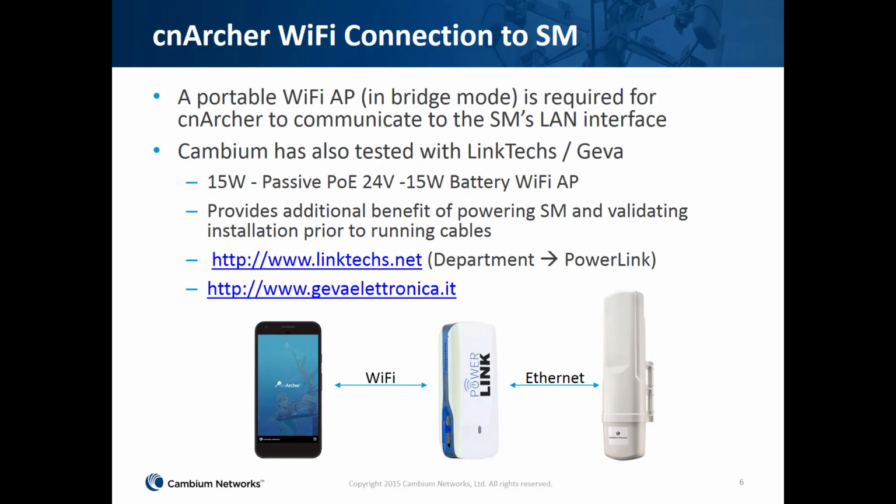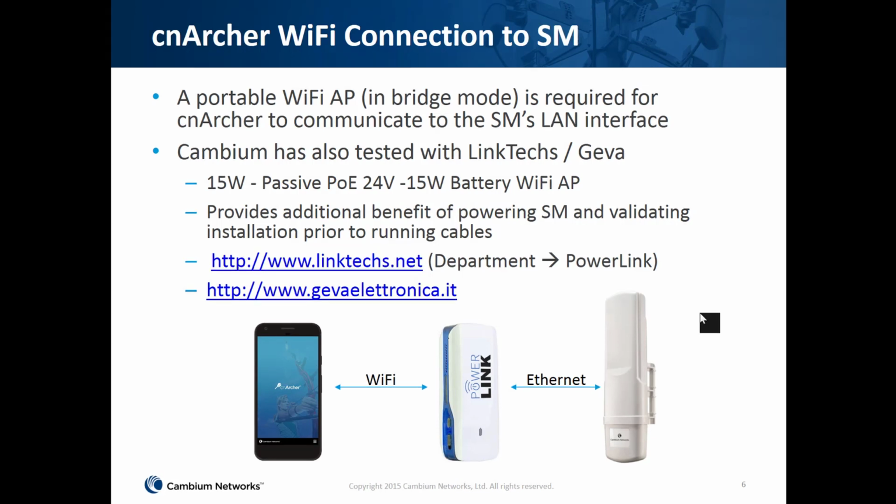So in order to communicate with the SM, the app does rely on your mobile device's Wi-Fi interface. We've tested with the PowerLink dongle, which has the added benefit of powering up the SM, but any standard Wi-Fi AP that's in bridge mode is sufficient to pass traffic and establish the communication.